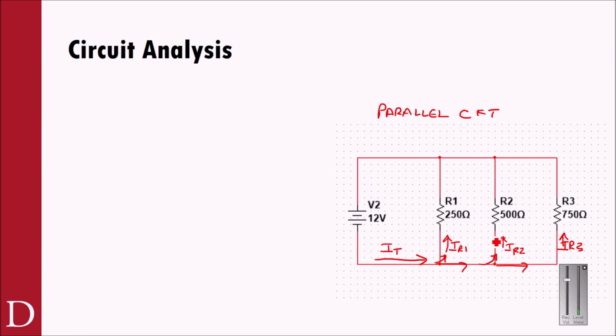somebody taking that exit. What's unique about that, though, is Kirchhoff's law says that if I take a complete path in a circuit, I have to consume that voltage. So it makes it a little easier, because now what I know is I know VR1 in a purely parallel circuit has to equal 12 volts. Why? Well, Kirchhoff's law says if I'm an electron flowing this way and I flow up through R1, if that's the only